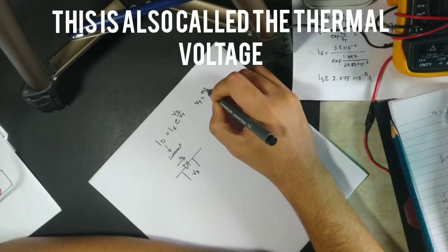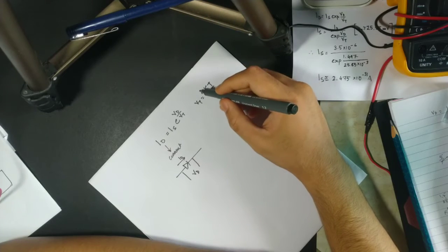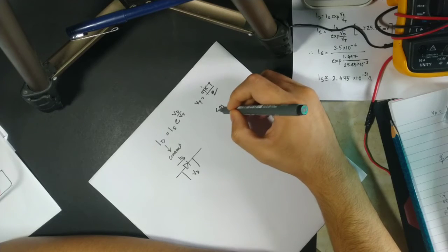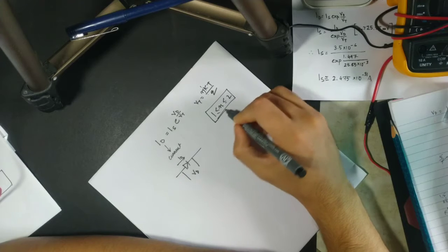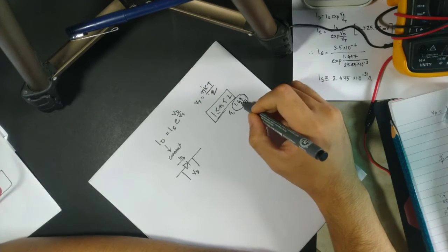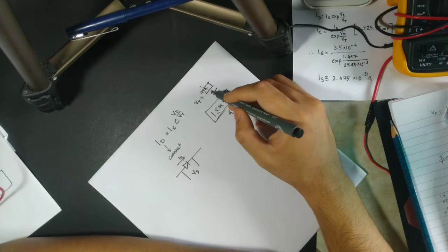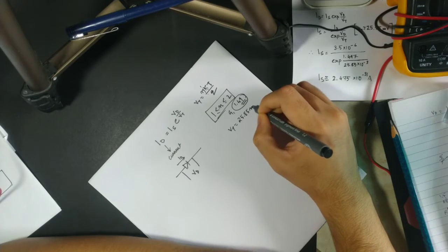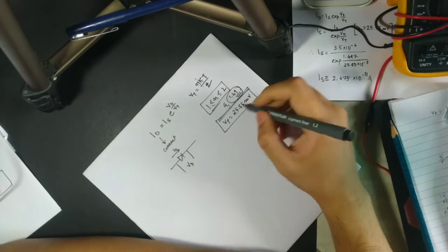Vt is equal to N K T by Q. Q is the charge of an electron, T is the temperature, K is the Boltzmann constant, and N is the ideality factor. N's value is between 1 and 2, and it depends on the material. Like for germanium it is around 1.49, so I'm using 1.49 as N, and since this is constant, taking room temperature, and Q is constant, I get a Vt value of 25.85 millivolt. This is for most of the diodes, and I have taken the same value for the LED.